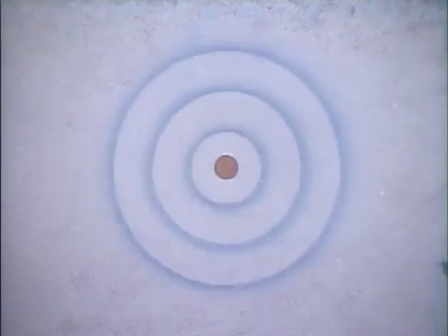The current flow creates a magnetic field that expands and collapses around the conductor. The relative motion between the conductor and the magnetic field caused by the expanding and collapsing induces a voltage in the conductor. This induced voltage is opposite in polarity to the applied voltage. The induced voltage opposes changes in current flow because it tends to cancel the effects of the applied voltage.